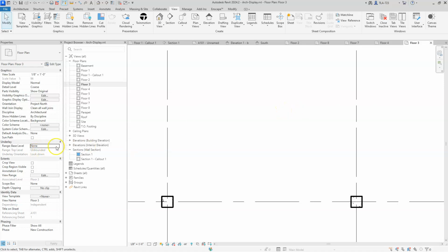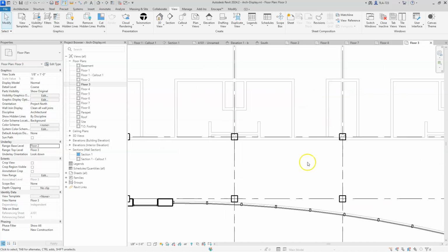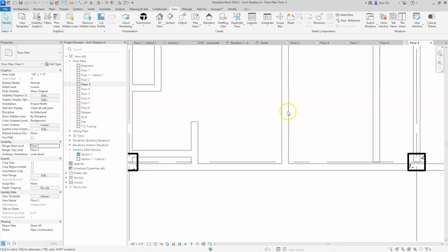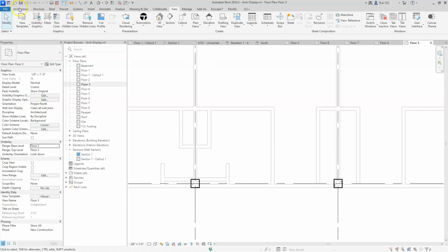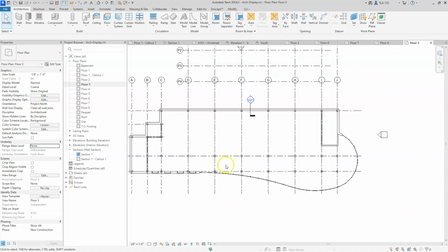Okay, so underlay, we can talk about some different reasons we might want to use underlay. I think you can use your imagination on that. But basically, when we are setting up things like stairwells or vertical alignment, sometimes we want to temporarily see another floor so that we can align the thing on this floor with it. And we can actually trace those objects when we're creating things like walls and columns and things like that. So it's a really handy tool to have, but just don't get yourself confused by it and leave it on. It's always a good idea to just have those things shut off when you're not drafting using those objects as a guide.